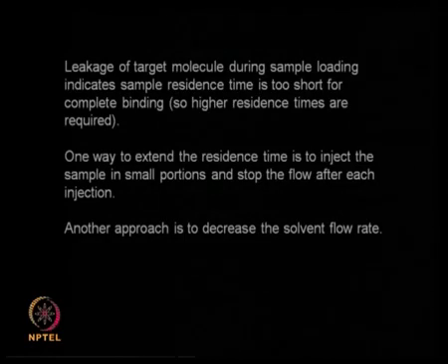But process wise what can we do? We can inject a little bit, stop, inject a little bit, stop, and so on. So that is one approach. The other approach is to reduce the solvent flow rate, because your residence time is too short, that is why your target molecule is getting leaked out.